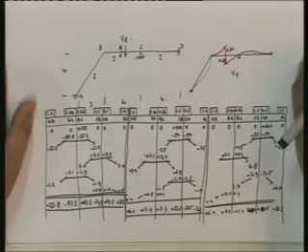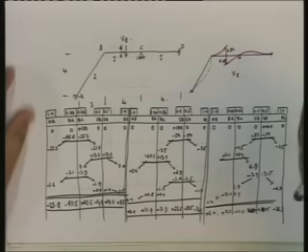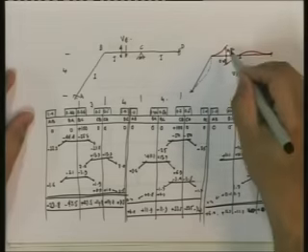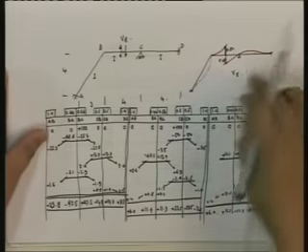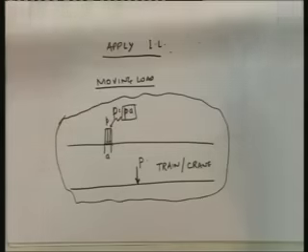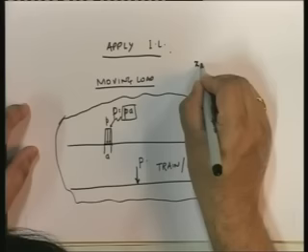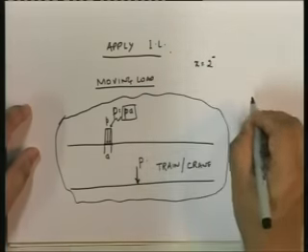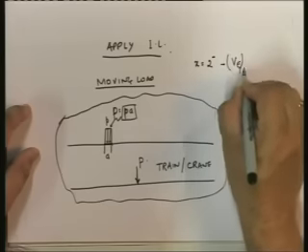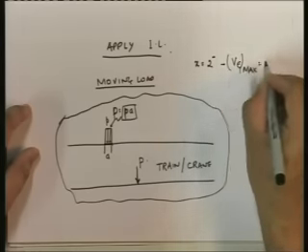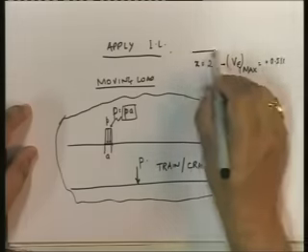This tells us that to get the maximum value of VE, which is the position of the load that we have, we need to put it just to the left. So x equal to 2 minus is VE max, and the value for a unit load is equal to plus 0.511.